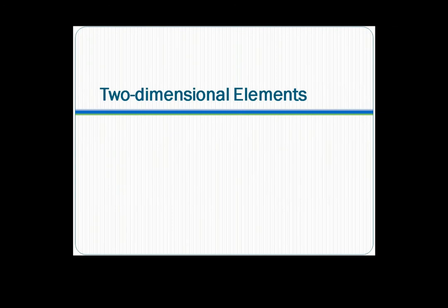Before this, we were looking at one-dimensional elements. From there, we looked into linear, quadratic, and cubic one-dimensional elements. We know that linear needs two nodes, so there will be two nodes and two shape functions, right? Then we derived the shape functions for linear elements. For quadratic, we need three nodes and three shape functions. Then cubic, four nodes, four shape functions, right?